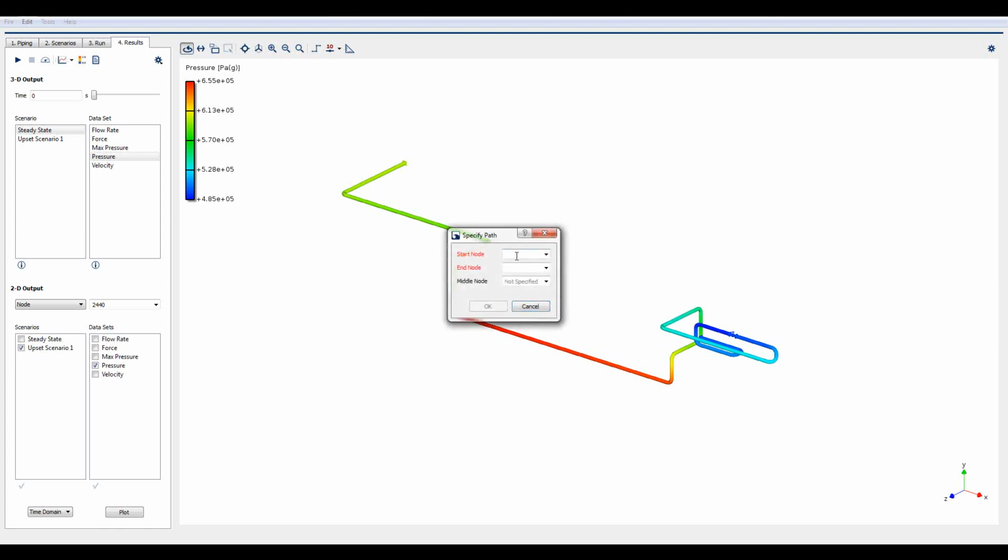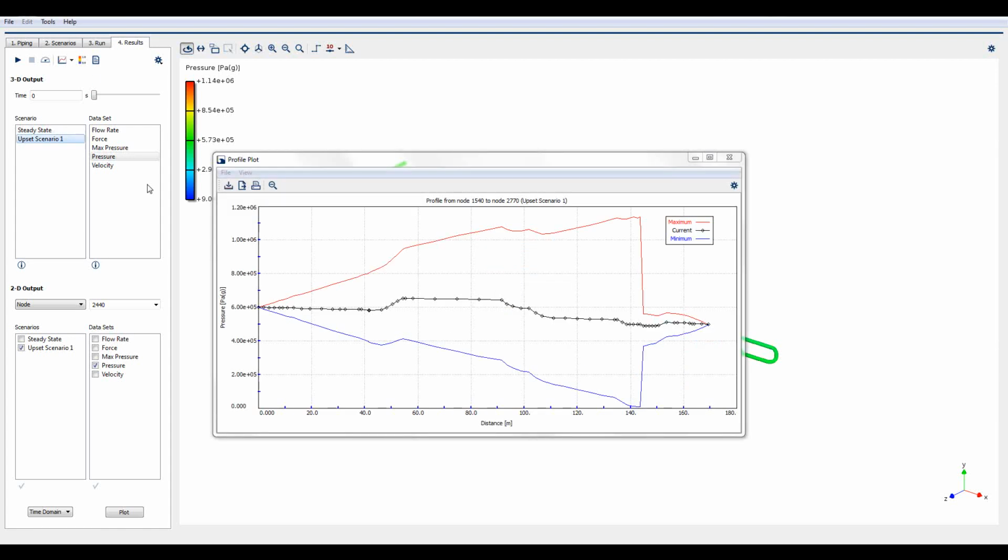As we plot the pressure profile over the length of the pipe, it can be seen that the pressure wave travels through the system. Since the pressure peak moves through the system as a wave, a differential pressure between elbow pairs results. It can be seen that a longer section of pipe will be able to facilitate a larger pressure difference, resulting in a larger unbalanced load.